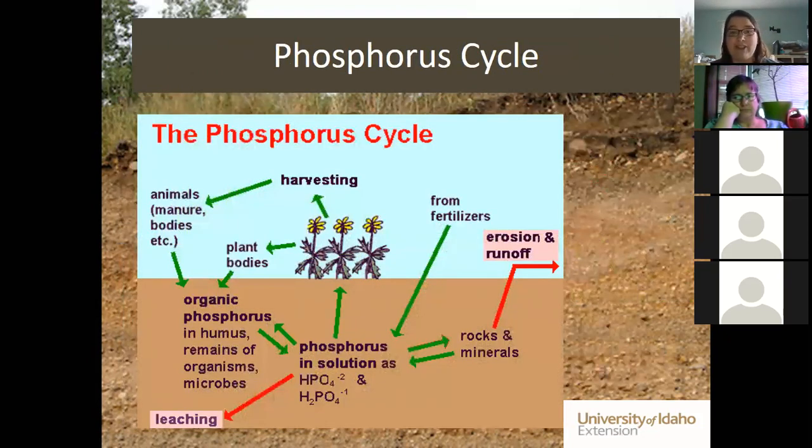Phosphorus has a much easier cycle. It's much more stable than nitrogen. Basically, you're getting phosphorus from dead plants and manures and animals to put it into solution. One problem is phosphorus can be unavailable to plants. You can have high phosphorus in the soil, but the plants can't get it until it's in a water solution. Not all phosphorus versions go into solution easily. They tend to stay as rock. Phosphorus can leach, but that's usually not a main way of getting rid of phosphorus.